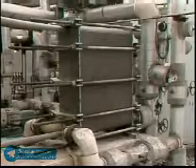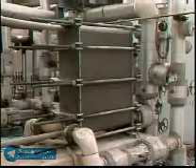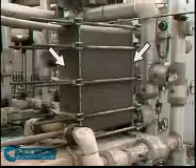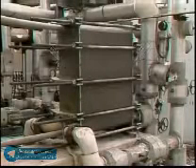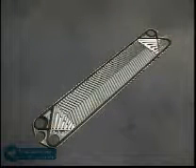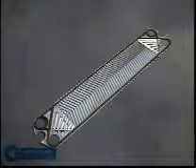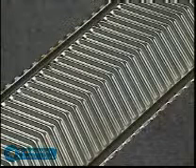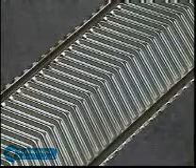All plate heat exchangers work basically the same way, so by looking at the components of a typical plate heat exchanger, you'll better understand how all plate heat exchangers work. This plate heat exchanger consists of a series of thin metal plates and two fixed end plates. The end plates are used to help support the other plates, and they hold the fluid inlets and outlets. The plates inside the heat exchanger have a corrugated or ridged surface. The ridges cause turbulence as the fluid passes over the plate. The turbulence helps increase the amount of heat that's transferred.